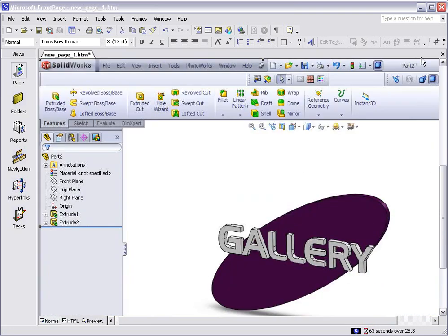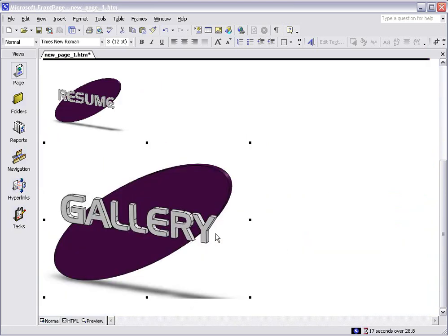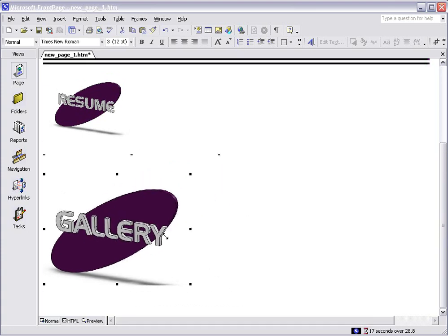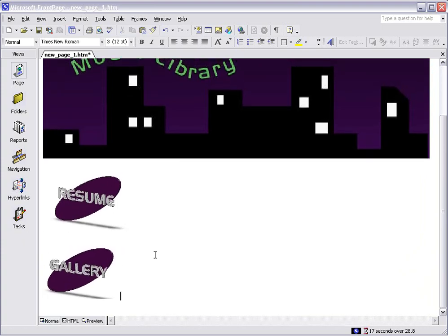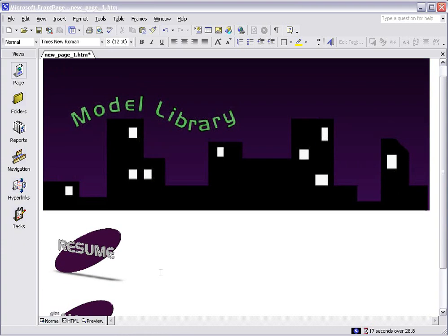And now here I'm going to use the crop tool again and do the exact same thing. Just surround that and then hit Enter. Again, be careful. In this case, I cut off a little too much. That's all right. Just make sure that when you do these, you could always hit the undo switch. I'm going to leave it because it's pretty close. We'll just squeeze it back down. Remember, don't rotate your model inside SolidWorks. Leave it at the same view perspective that it was at, and then they'll look nice and organized like these appear to be.